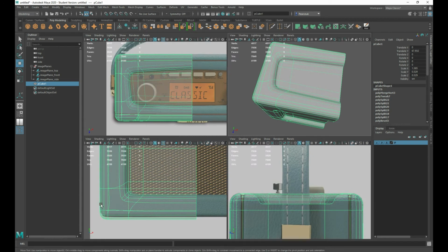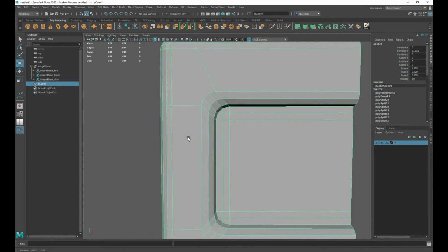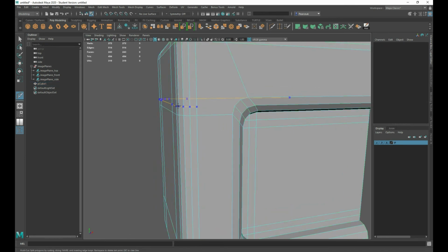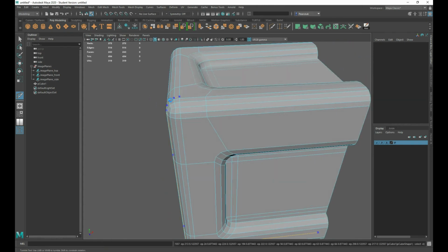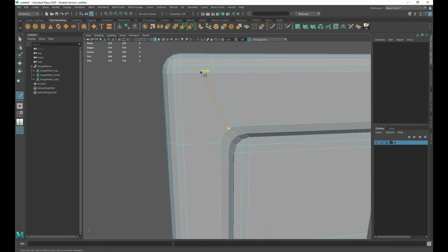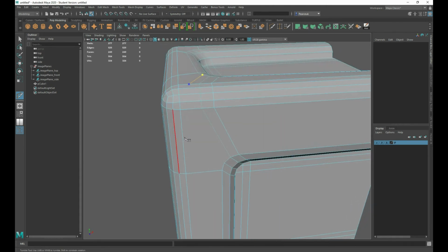And it's starting to look all right. We've got a few pinching bits here. That's because this edge doesn't go anywhere. So I'm just going to tie those off. I'm just going to put in an edge loop, say there. Or actually, what I might do is come up here and just tie it off there, rather than taking it all the way around.